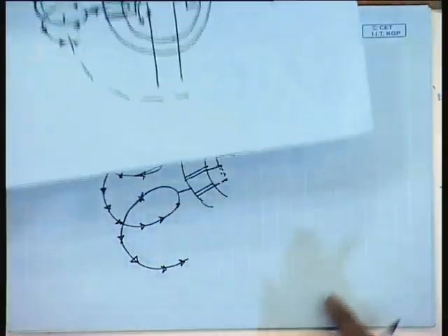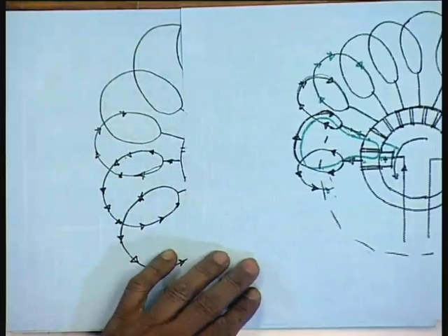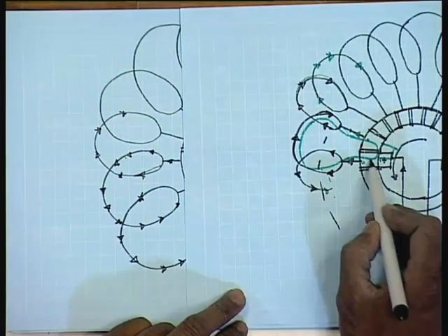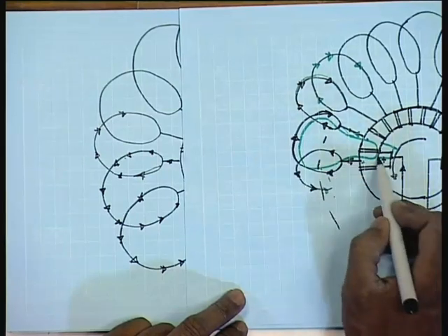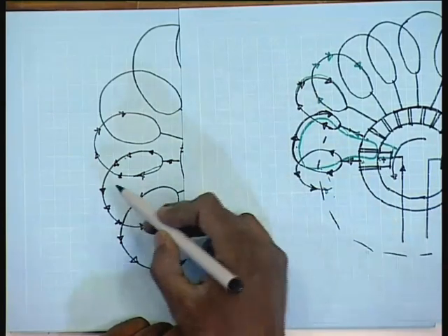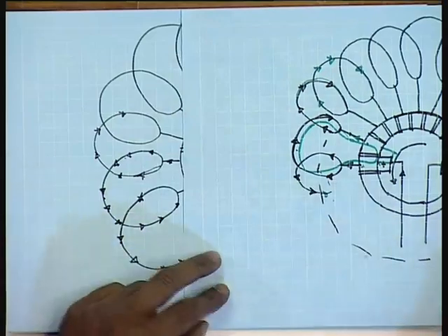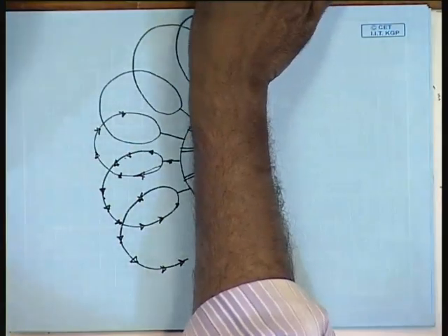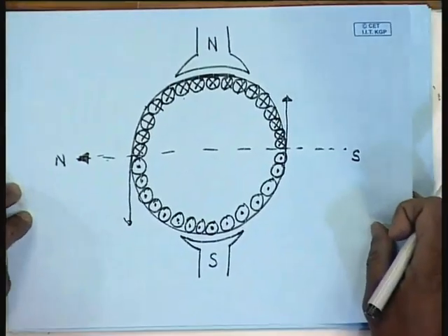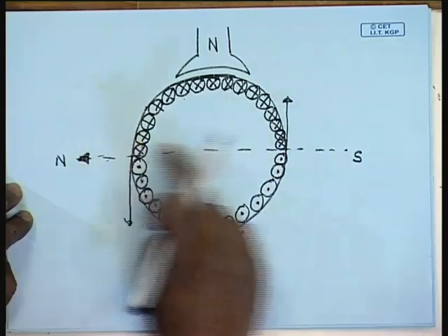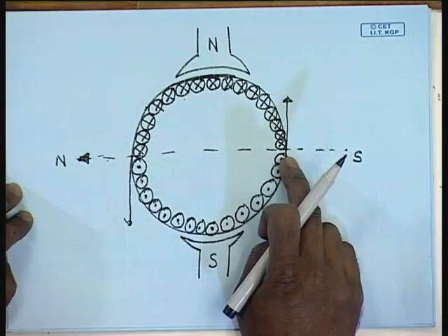Comparing the direction of these two coils, we see that the direction of the current that was shorted, which is said to have undergone commutation, has changed in that coil. Therefore, the coil in this picture that undergoes commutation, before commutation it had a dot current, and the corresponding other side has a cross current and the corresponding side has a dot current.